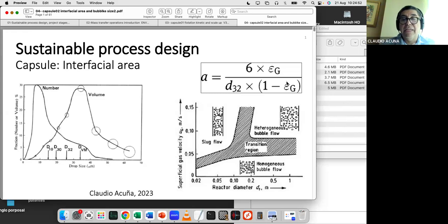So then you can go deeper, perhaps using a different approach, because you tried a Klimpel model with continuous tanks in series. Okay, you remember? Then we can come back a little bit, changing the kinetic distribution model to see what happens with the equations, to scale up.